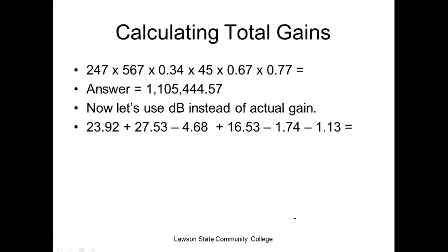So when I'm giving you losses in a communication system, I'm not going to give you a number. I'm going to give you a loss in dB. If you knew how much loss you had in your cable, how much loss you had on your transmitter, and how much loss or gain you had in your amplifiers, all you've got to do is add those dB up, right? You don't have to even get out a calculator.